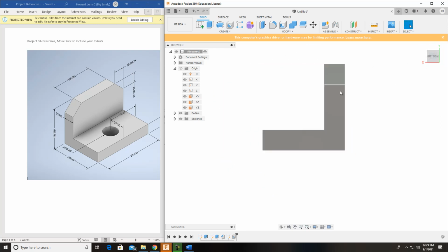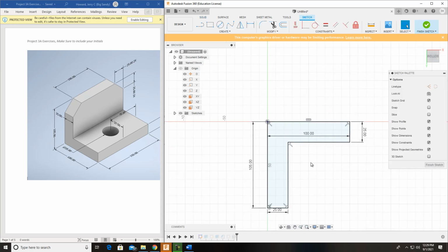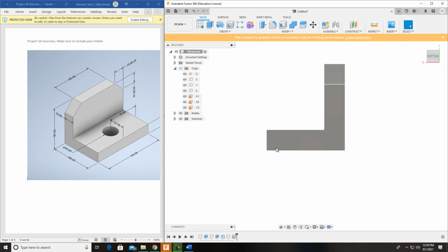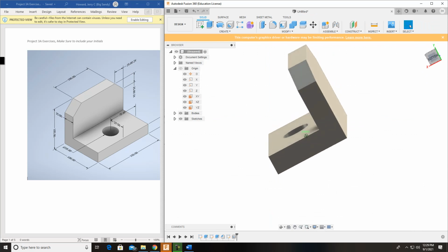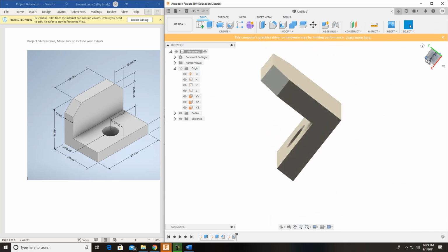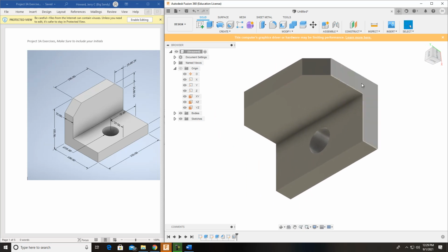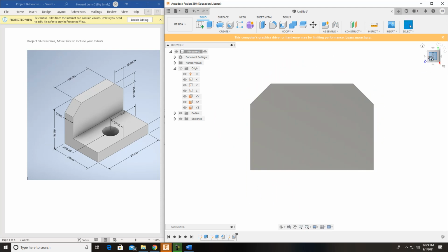Check this out. My original sketch, let's say I need this to be, I don't know, a little bit shorter than what it is right now. Instead of 100, it should be 95. You go back and find that sketch, double click it, it takes you right back to it. And then you can just double click here, 95, enter, finish sketch, and check this out. It updated it. Y'all see that? It might have been hard to see that exactly, so let's do another one.